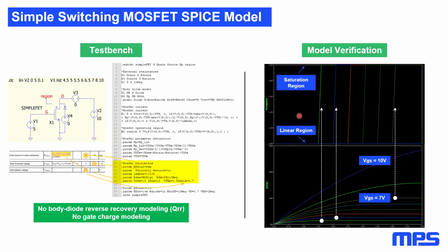From the theory, a MOSFET is generally and successfully modeled as a voltage-controlled current source, a variable transconductance, which represents the channel conductivity. In parallel to this, there is a diode representing this body diode. The channel transconductance parameter, here we call it Kp, is a function of the technology, the physical property of the MOSFETs, and includes the temperature dependence of the MOSFET resistivity.